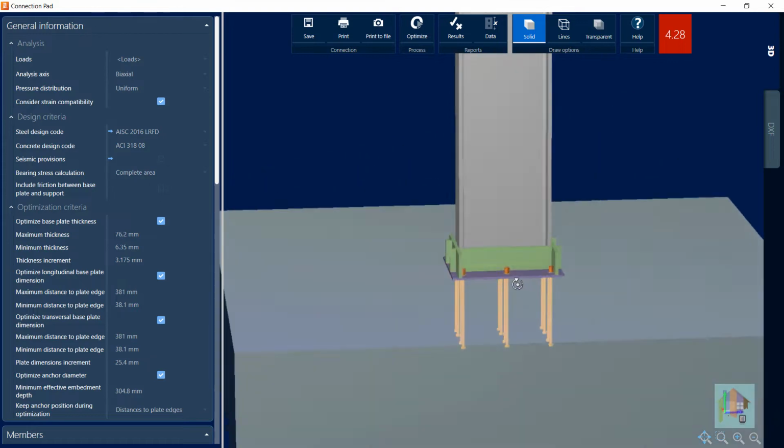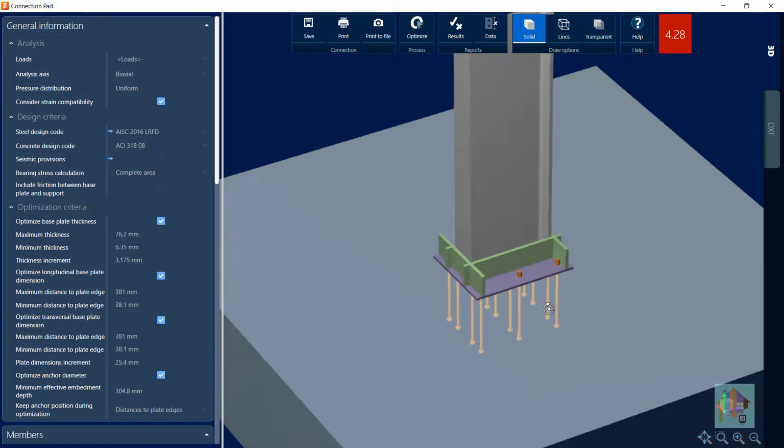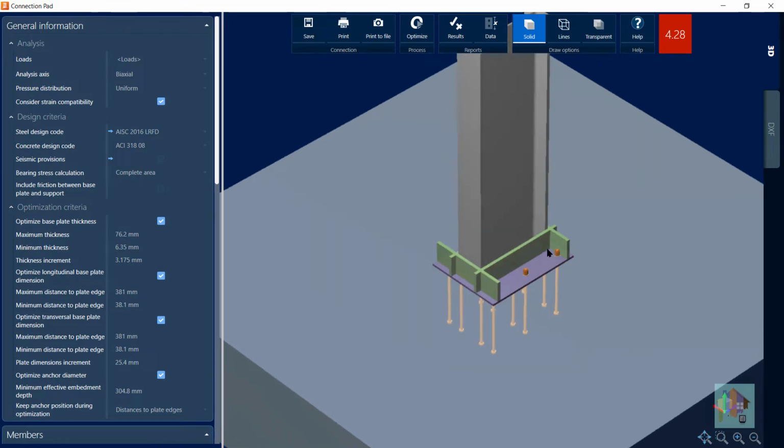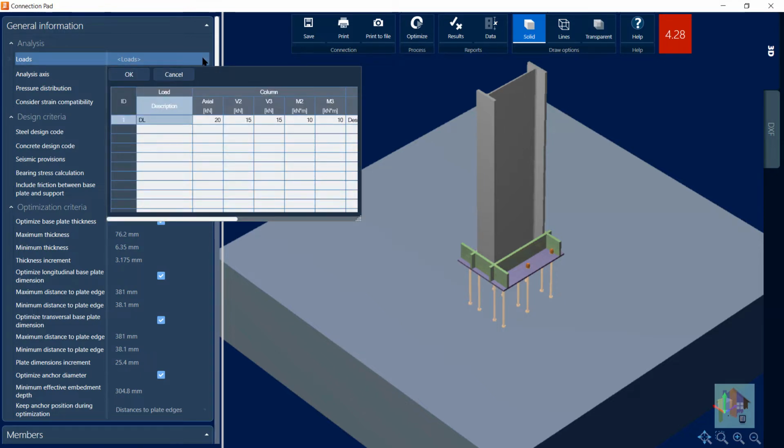But for any PEB structure, the steel columns are not extended or tied with the foundation. It is connected using a base plate anchor bolt arrangement, and it is very important to evaluate this base plate connection before support assignment. We need to finalize the level of fixity along with the support condition.